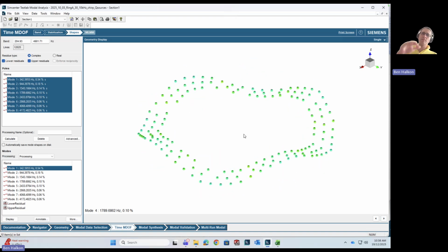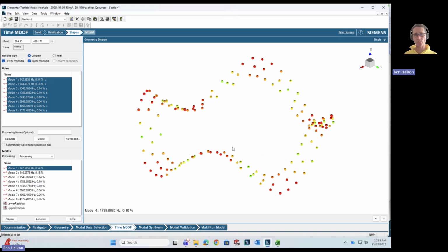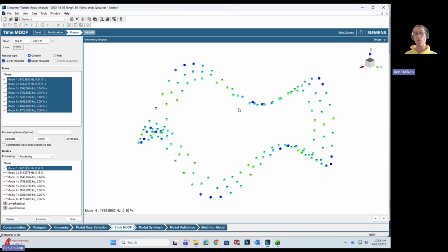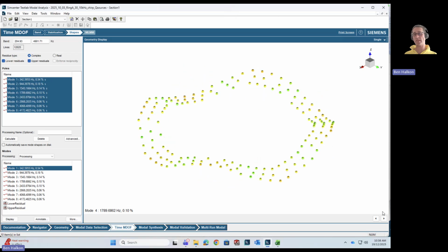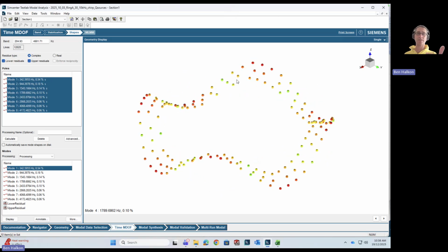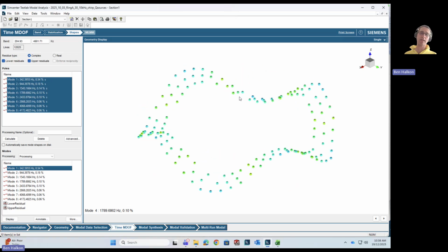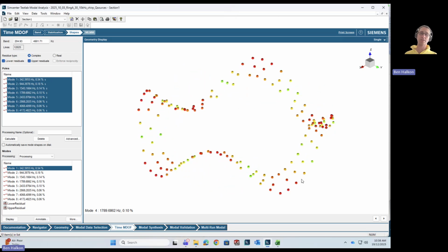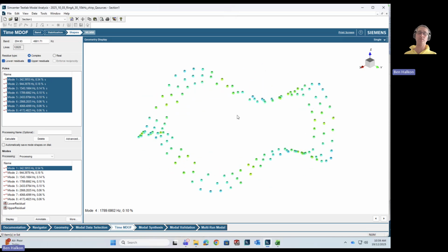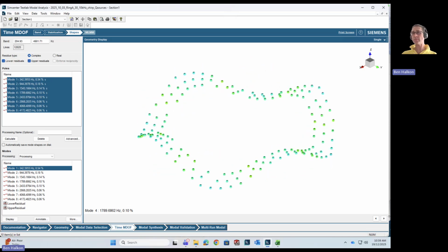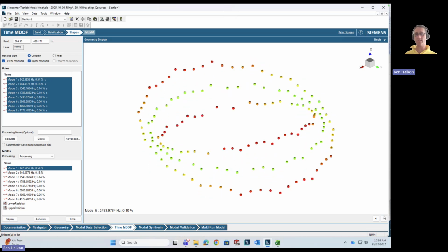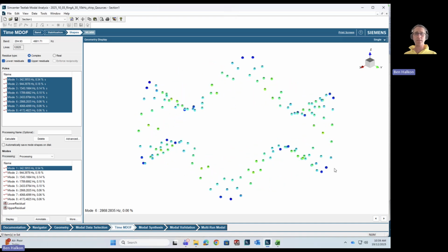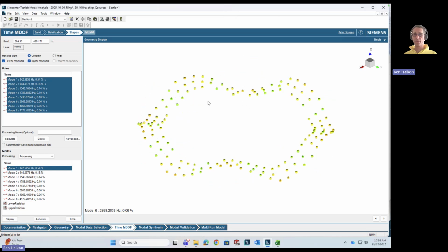Now these are all modes that exist for this rectangular structure with vibration that's primarily in the z-axis, so on the optical axis of the laser vibrometer, because of course the vibrometer is sensitive in the optical axis direction, and also we're exciting the structure in the z direction, which is coincident with the vibrometer optical axis. This video is now very long. I understand that. That's the m equals 1 torsional mode. That's an axial mode. I think m equals 4.